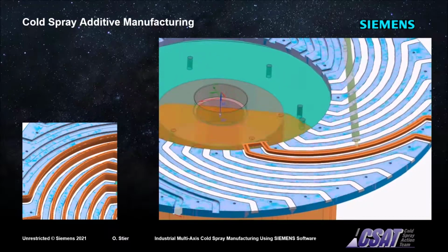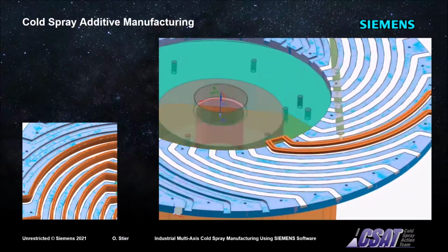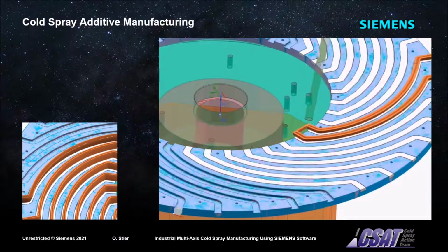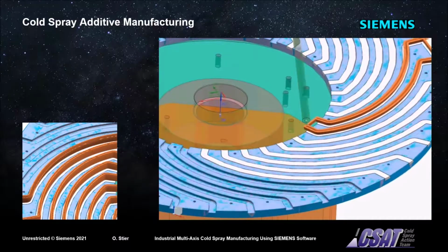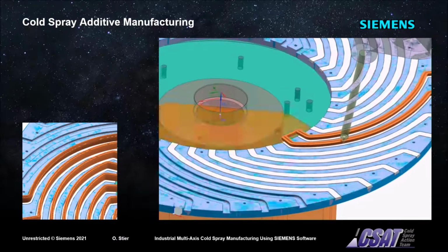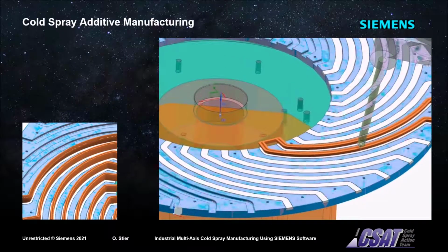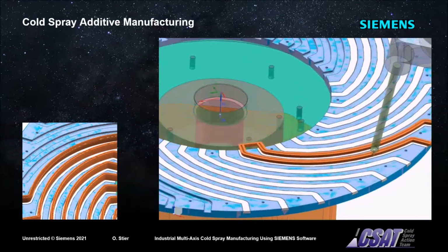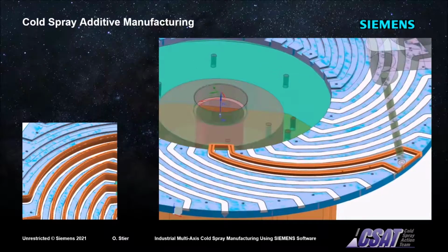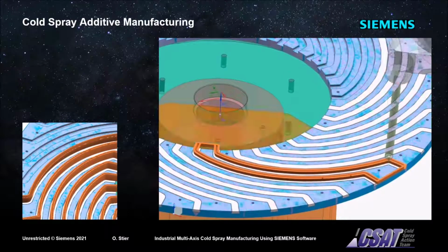As an example of net-shape additive manufacturing, we show an existing 3D printing process for copper in the mirror of NX-CAM simulation. Along the spray path, the nozzle maintains constant standoff distance, constant tangential speed, and piecewise constant lateral tilt angles. The productive spray path consists of pairs of rails.